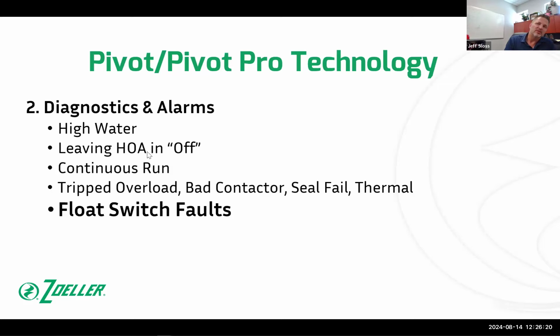What we did is we said, well, we can't turn it back to auto because that's not a safe thing to do. We can't do that automatically because the panel doesn't know if it's safe to do that. But we can give an alarm. So we give an alarm after 4 hours that, hey, somebody left this panel off. Is it supposed to be off? And they can override that alarm if they don't want the alarm and that kind of thing. But the point is, we're giving all of these alarms. It's a smart enough panel to know that something's wrong.